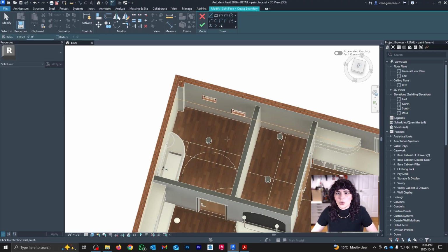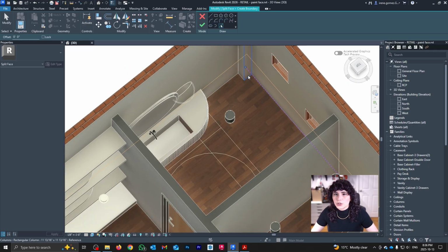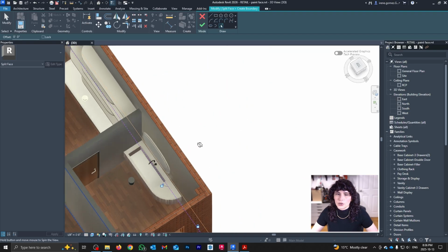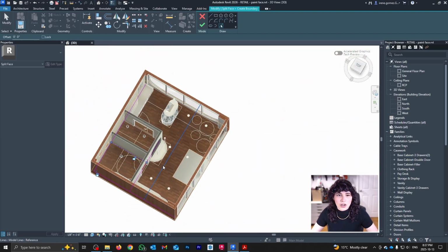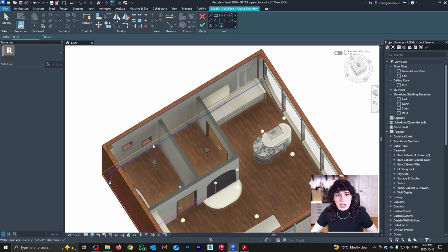This time, instead of drawing the lines, I can use Pick Lines. Let's say I'm going to pick my wall boundaries. So I can click on this guy, this guy, this guy. Did it pick? There you go. Now it picked it. Let's say this guy here, and this guy here. So this is another way to do it, basically following the boundaries of a room.